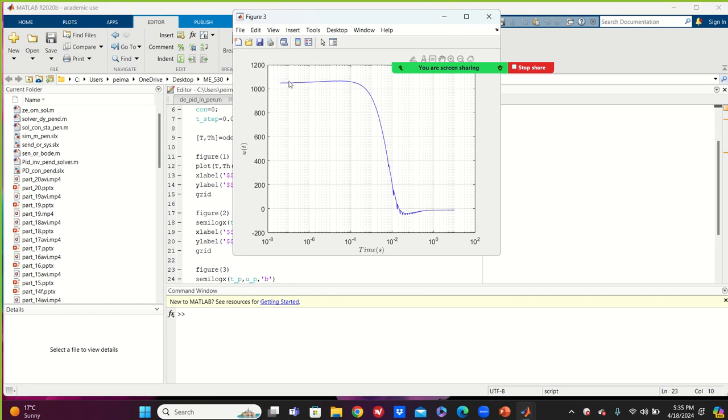That is too much. So when you're tuning your gains, not just in PID control, but if you go to a nonlinear control scheme, name it from sliding mode control to adaptive control to delay control to whatever MPC control, you have to be careful that this is not out of the range of the actuator that you have in your robot or in any system. Okay, this can be a saturated signal. Okay, assuming that it is not. And I just want to show you.